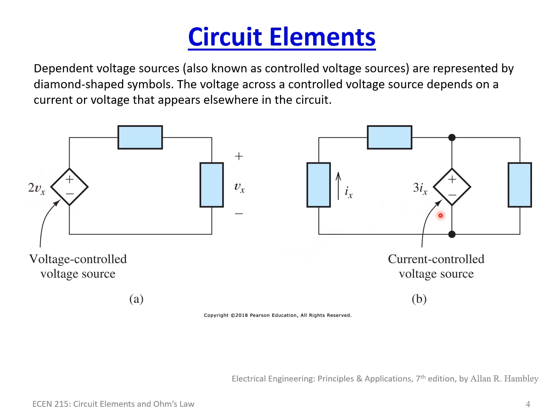Same thing here in the case of a current controlled voltage source. In this case, this is a voltage source signified by the plus and minus sign. In this case, the voltage will be 3 times whatever this current going through this element is, in this direction. So if this current is 1 amp, then this power here would be 3 volts. If the current actually was flowing in the opposite way, with the arrow being this reference, in other words, this is now, say, 1 amp going this way, in the opposite direction of the arrow, then it would be 3 times minus 1, or minus 3 volts.